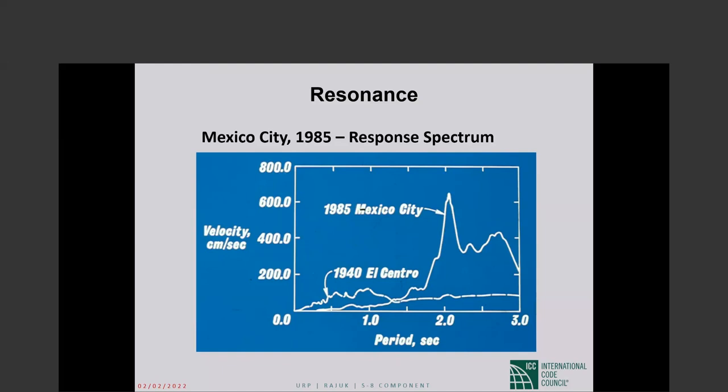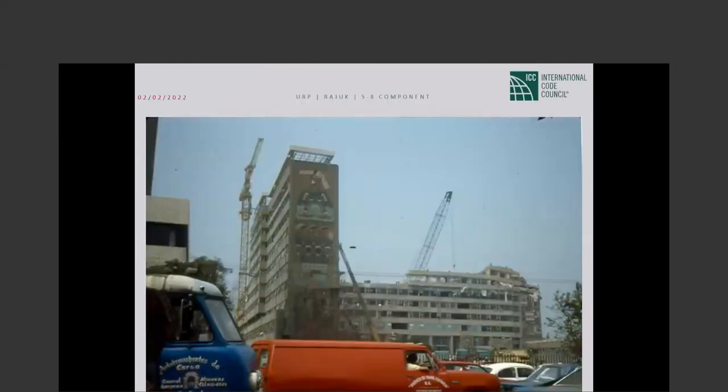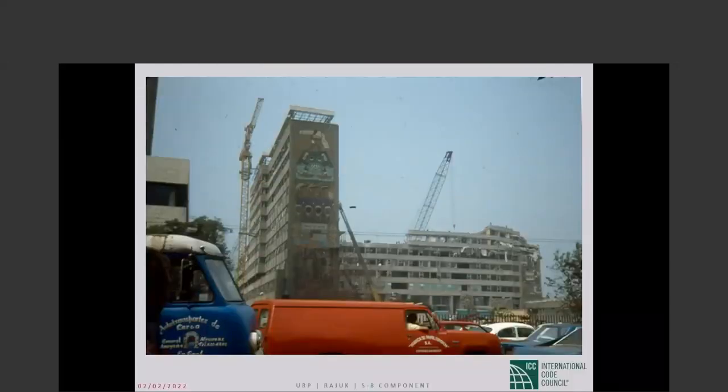so you may start with a period of, put it, 1.5 seconds, and as the structure goes through the earthquake, the period may lengthen into 2 seconds, and then it is in big trouble because that is the predominant period of the ground motion. So you would expect medium rise buildings, period of, let us say, 1.5 to 2 seconds, to be the most affected. Now that's exactly what we observed.